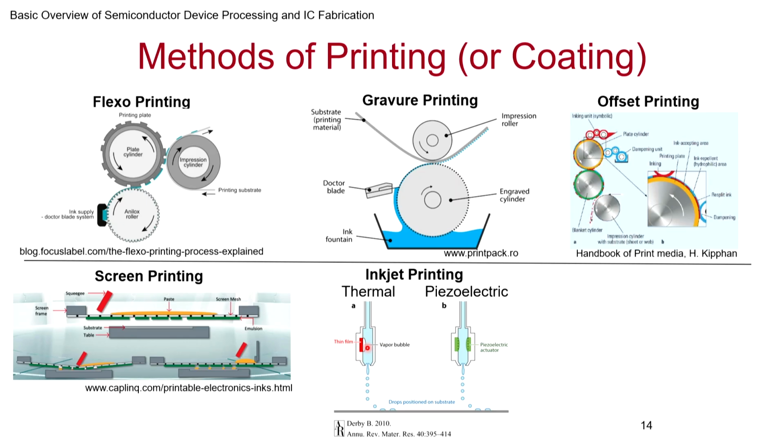You might have heard of it. It's a thermal process where by heating the air pocket, you increase the pressure and dispense the liquid. So wherever you want to dispense, you heat the bubble, ink gets dispensed, then you cool it, then it doesn't get dispensed. Or you can have a piezoelectric approach, where you apply a bias, the pressure changes, and so ink is dispensed. And when you don't want to dispense, you change the bias, so the pressure reduces, and the ink is no longer dispensed. So this is a print on demand type of inkjet.